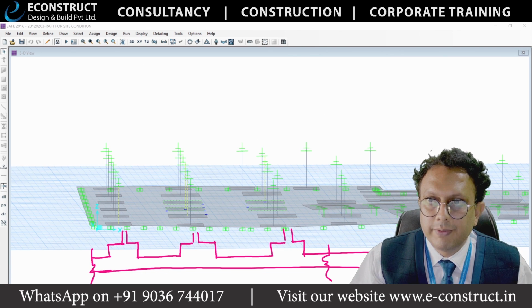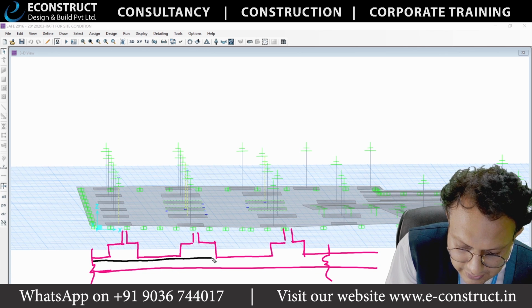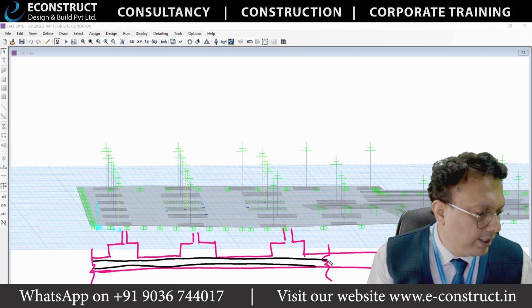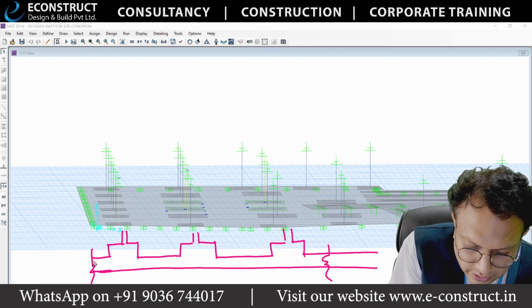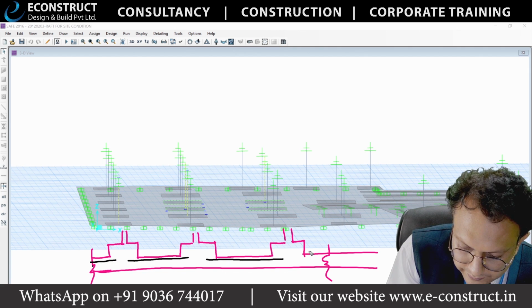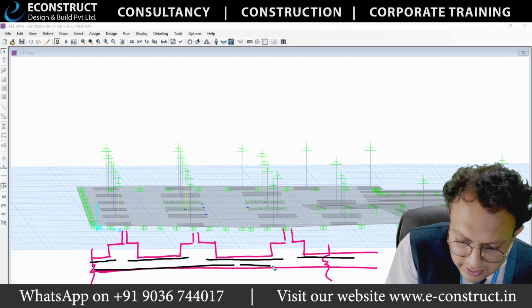So the reinforcement of this also would be a little different. The top rebar is definitely required here, the bottom rebar is definitely required here. Sometimes it is like this, and sometimes, if the distance between the two is very high, it will be like this, and the bottom rebar will be straight.